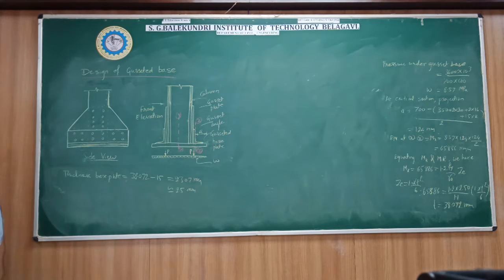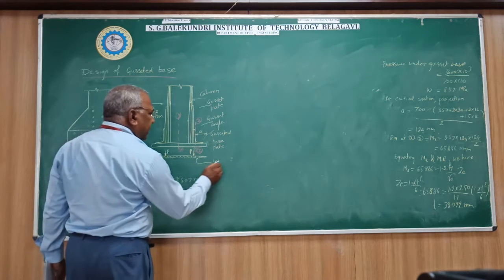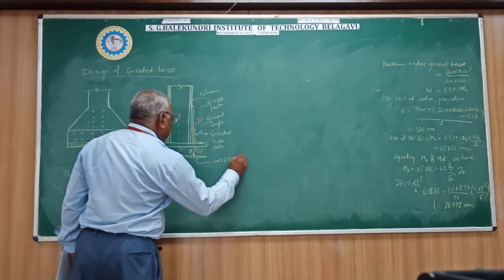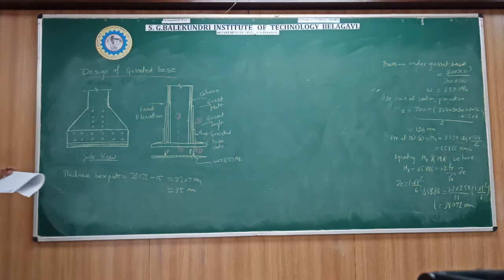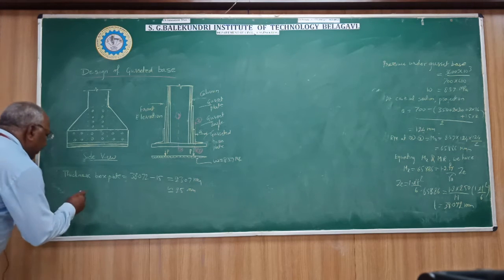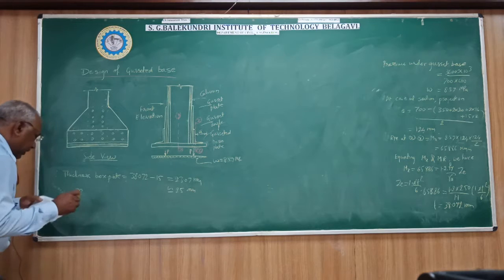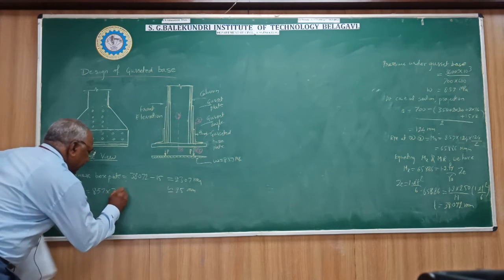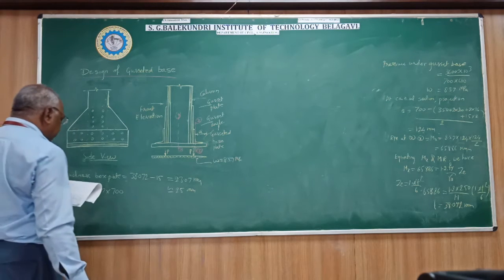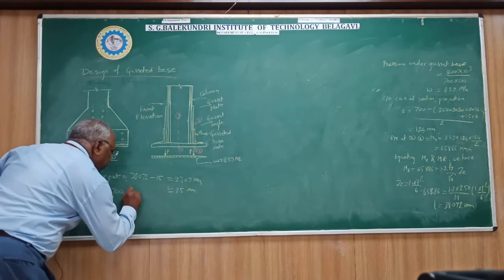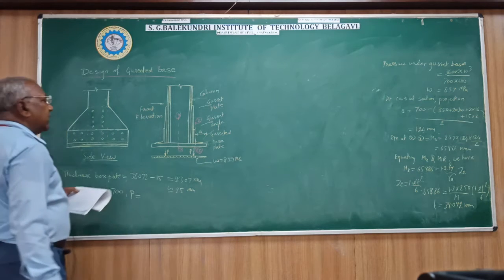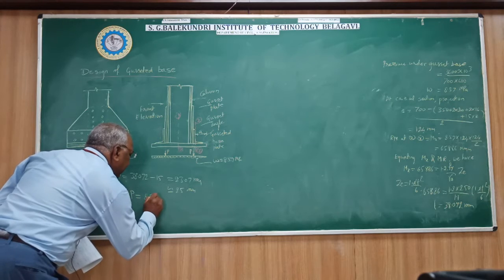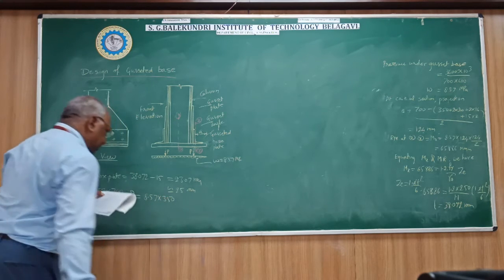Now the pressure distribution under the base plate is W equal to 8.57 MPa. The force P will be found by 2P equal to 8.57 into 700. So the point load acting at the junction of the gusset angle and the gusset plate is 8.57 into 350.